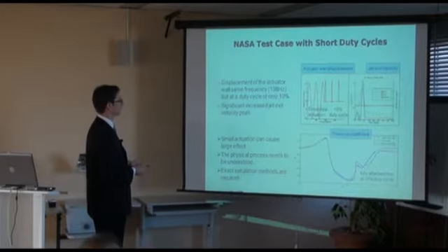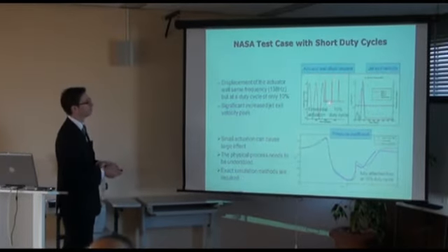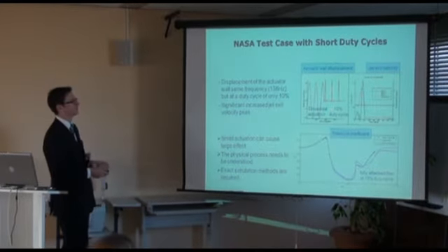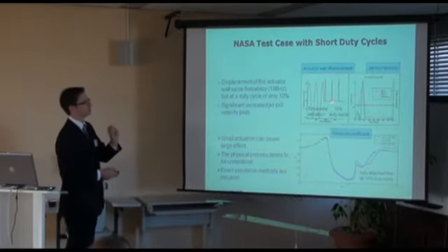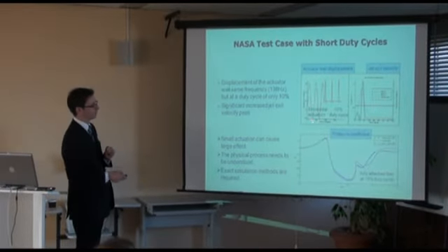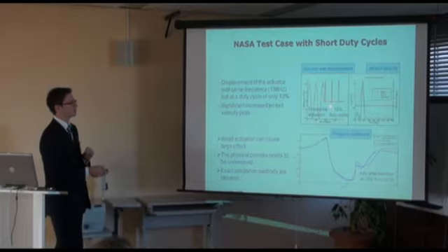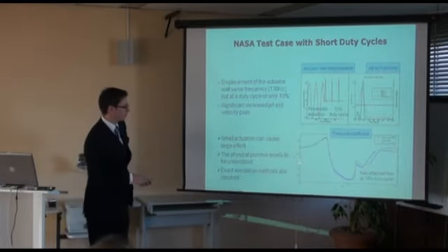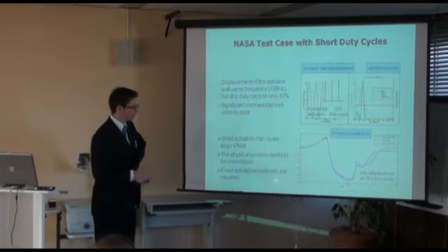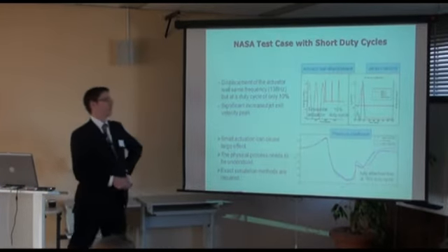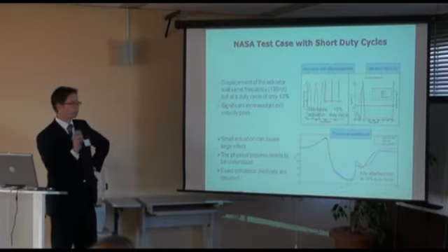So they had a small peak of velocity coming out of the small holes. Before they had this big actuation, now only small pulse jets, and therefore you can see here in the pressure coefficients over the length of the duct, they got a complete attachment of this flow by only actuating 10%.